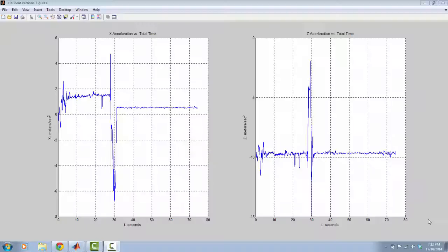Alright, so now I will be going over the data that we collected during our flights on demo day. This is one of the flights that we had. This is the first flight. Looking at the data that I graphed here, it is the accelerometer data collected from the IMU in the X and Y, or X and Z axes. You can see on both there's a very large jump in the accelerometer data followed by some oscillations. The first jump is the force at launch.